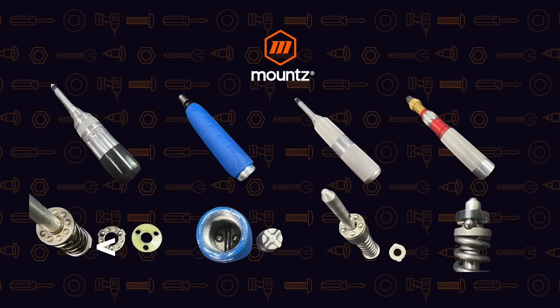And so as the twisting force happens, once the spring gets compressed to a certain value, those ball bearings will then move into a different lobe here or indentation on that particular set of mechanisms. And that's how this particular style of tool works.